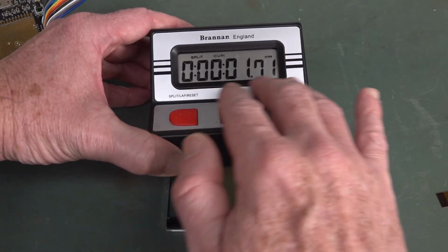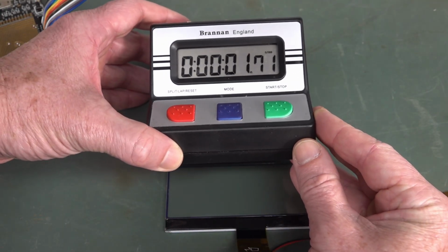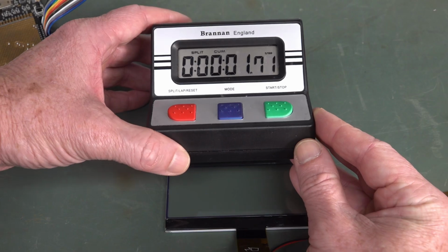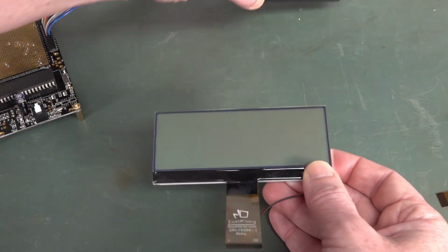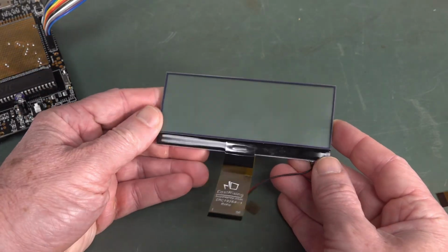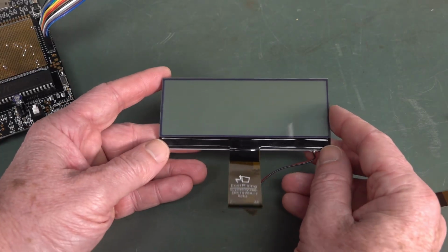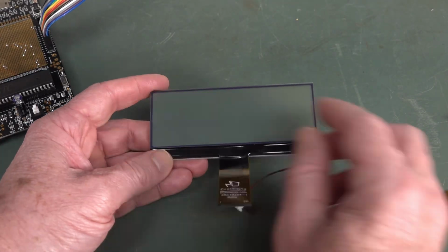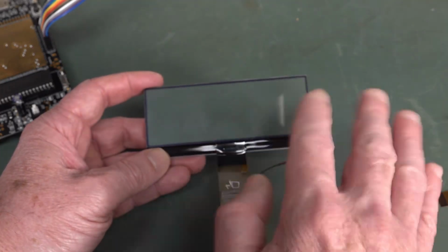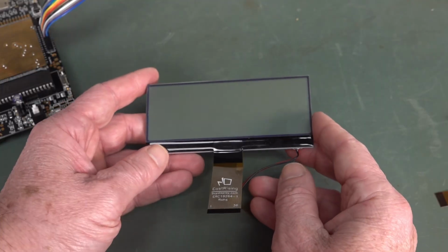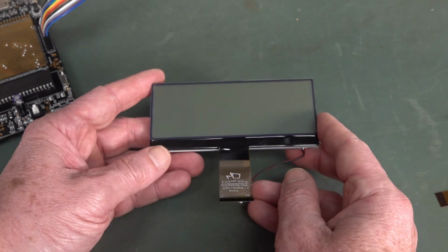Custom 7-segment displays like this, you can get really good contrast on them. That's the best in terms of contrast, but it just limits the functionality. And I thought, well, I don't want this to be a jack of all trades, master of none. I thought that not only would I have a bigger display, but I'd make it full dot matrix as well, just for some versatility. So you can change the size of the font if you want. You can have multiple timers going and things like that. You can't really get that flexibility with a custom 7-segment LCD.